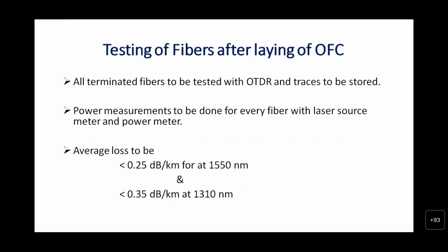Testing of fiber after laying of OFC is also mandatory. All terminated fibers to be tested with OTDRs and traces to be stored. Power measurement to be done for every fiber with a laser source meter and power meter. Average loss to be less than 0.2 dB per kilometer for 1550 nanometers and 0.335 dB per kilometer at 1310 nanometers.